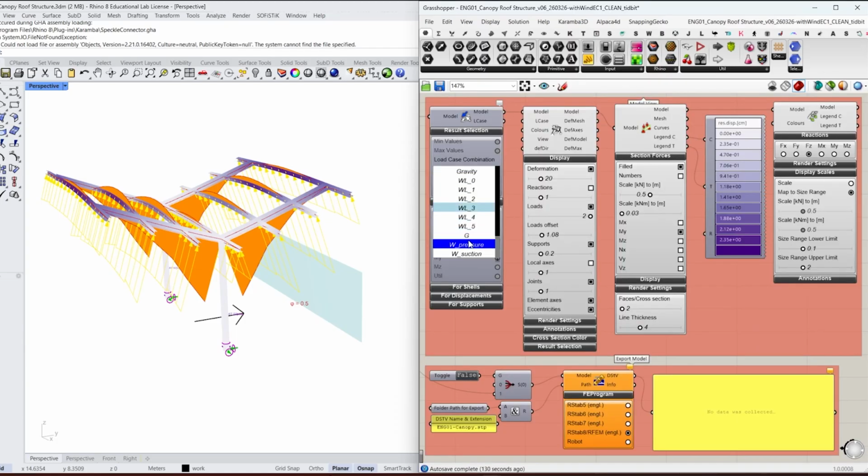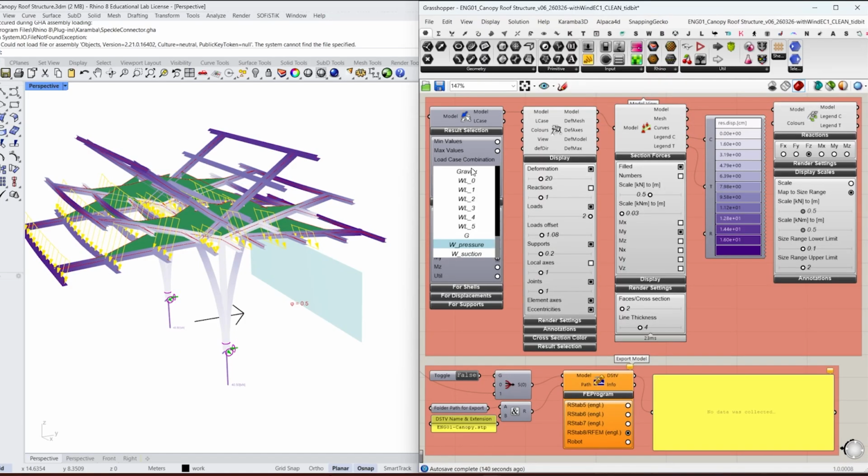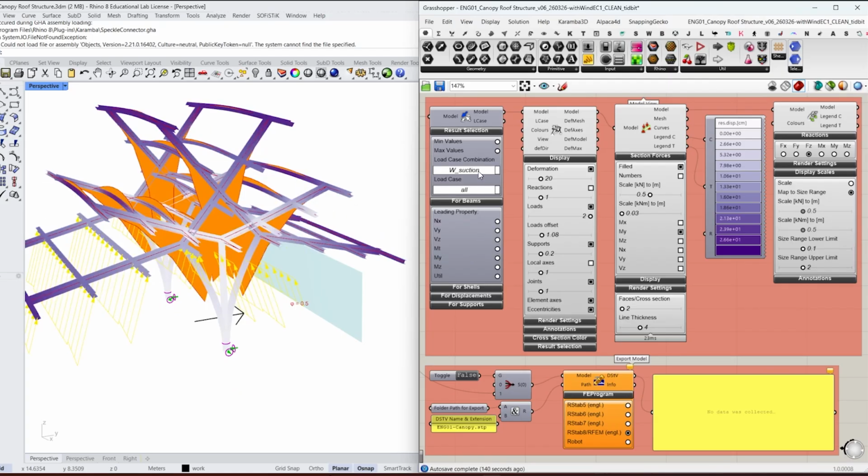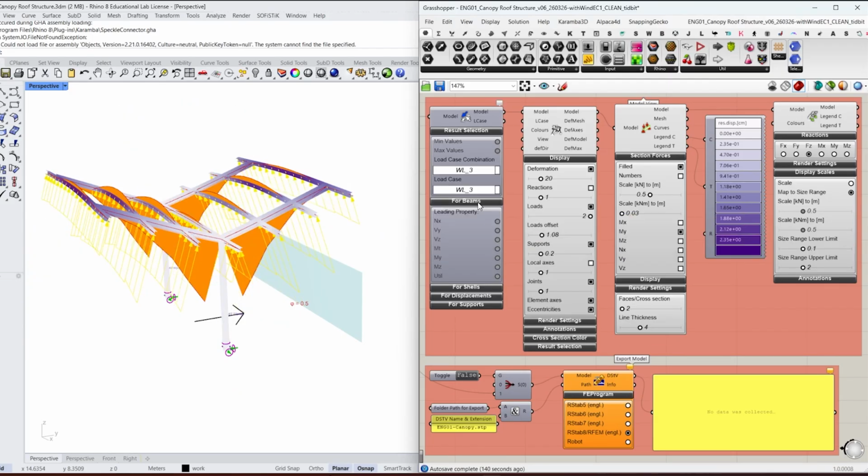The next step will be to use the force coefficient to define mesh loads for the 6 loading conditions prescribed by the Eurocode.